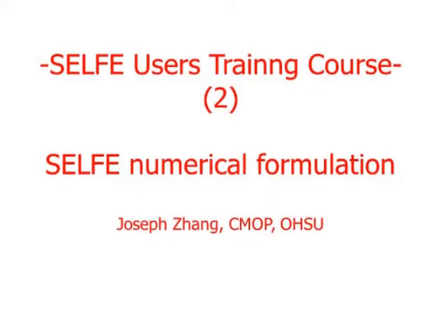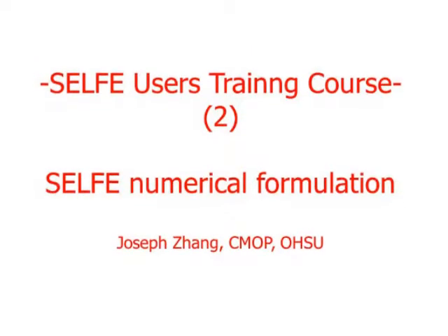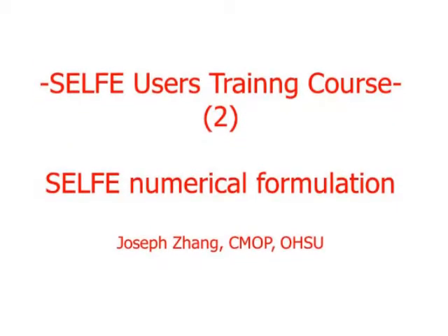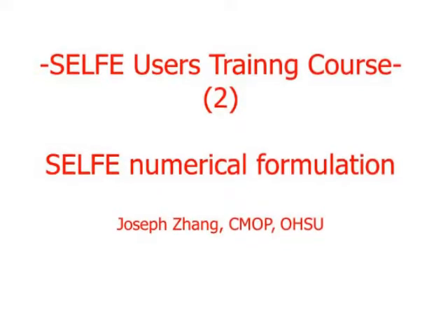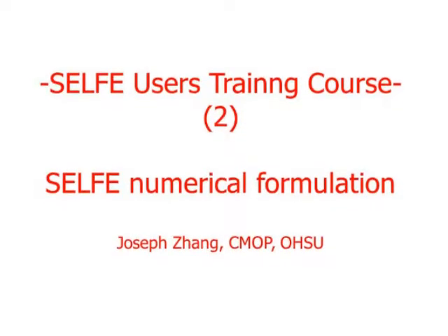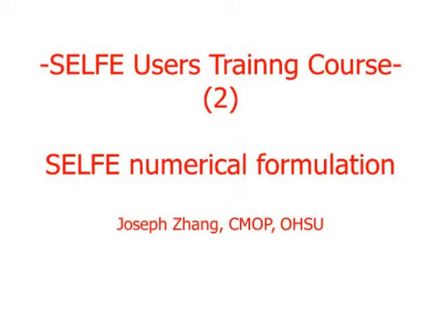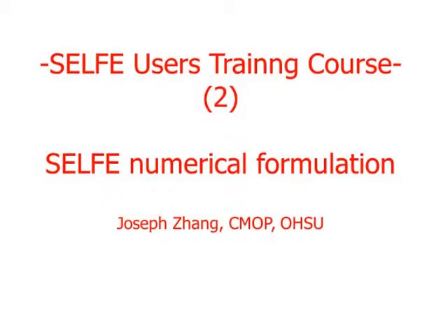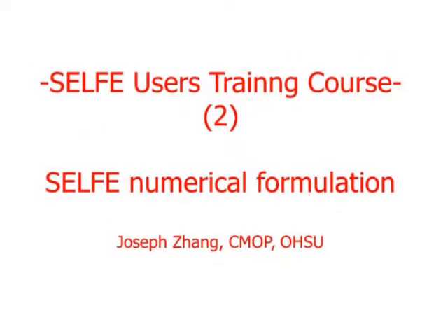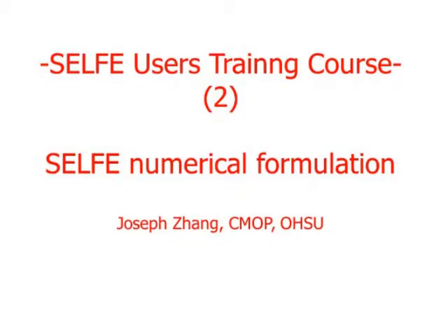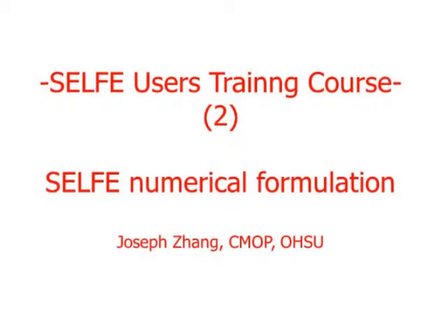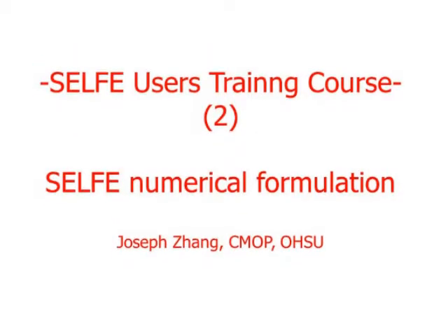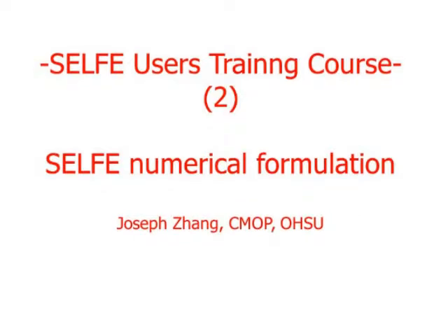The combination of horizontal and vertical discretization leads to the basic computational unit in 3D being a prism. But in this case, a prism will have uneven surface and bottom, because the terrain following coordinates are used. Of course, the S coordinates are ideal for shallow regions, and Z coordinates are necessary to stabilize the deep regions. That's what we found out the hard way. And the sigma coordinates are used in place of S coordinates whenever needed.